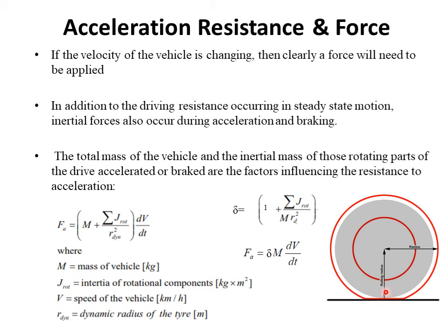This will be different for different surfaces and conditions, but there will be a change in the effective radius of the wheel, and that effective radius is taken as r dynamic, or rd in certain textbooks, the effective rolling radius. Okay, and this is the actual radius. So r dynamic, or rolling radius, or rd, all represent the effective radius.